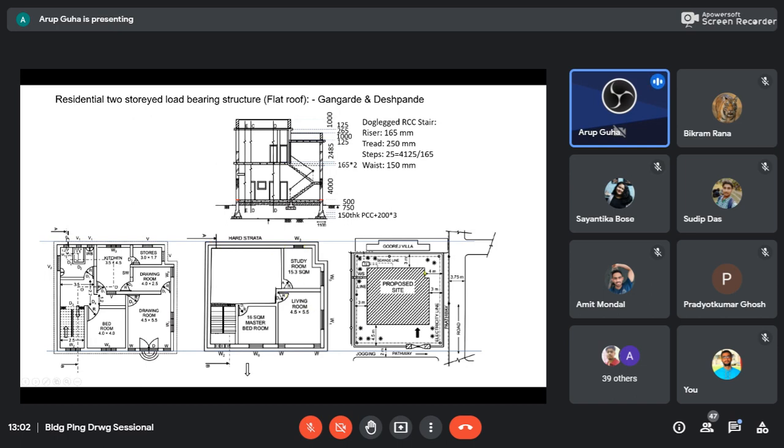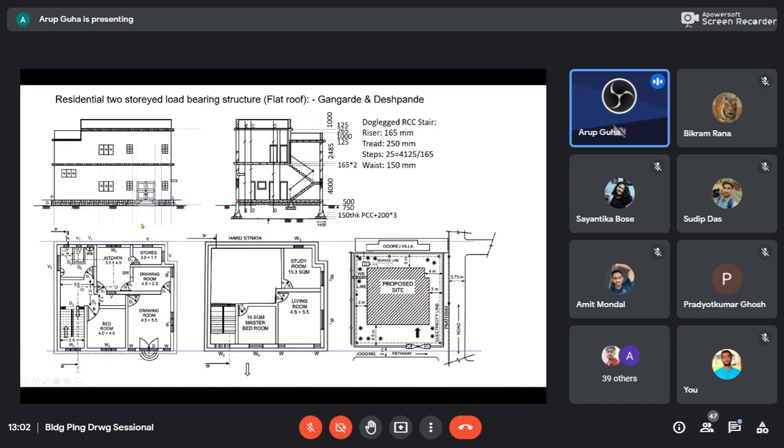Now, this is probably at this level. I don't see any levels over here. Levels must always be given. And then these are the building heights, sectional views. And this is something like a site plan. Okay. This is your elevation. We have taken vertical lines from these walls and got the guidelines over here and drawn the elevation from the plan.